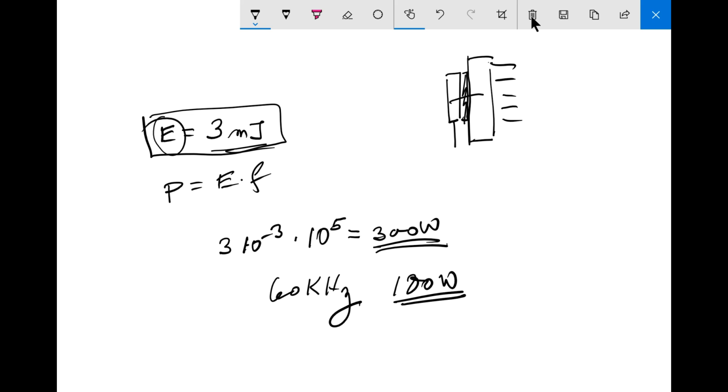Then there is a thermal resistance between the junction and the case, which is a crucial number, and we'll see in a minute what the value is here. And then there's some insulation in between, that thermal pad, and so the total could come up to be around, say, 0.5 degrees centigrade per watt.